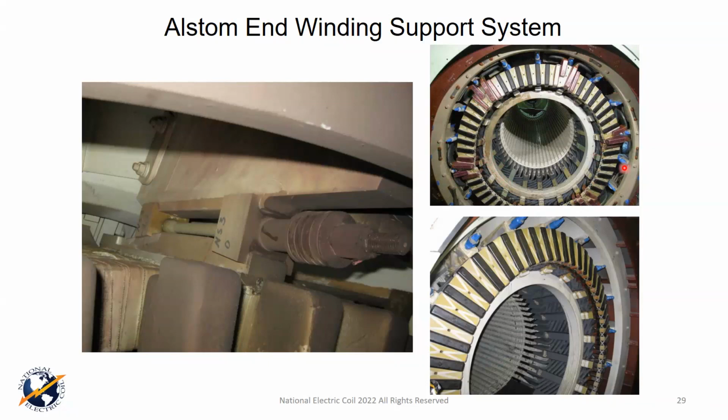Now, you see all that blue that's in there? I wish I could be asking you this question, but I gave the answer before. This is before this unit's painted. We go back to this diagram. If I paint up this whole threaded rod and everything, and I paint up these areas of these lands and stuff like that, that paint will essentially glue everything in place. So this is right before painting, and they have the threaded rods covered up, and they have the areas on the slider also covered up so that it can maintain its functionality after it's painted. And then obviously it's extremely important to account for all these pieces of tape, and make sure they're cleared after the painting and that these surfaces are cleared. So that gives you a little bit of help here.